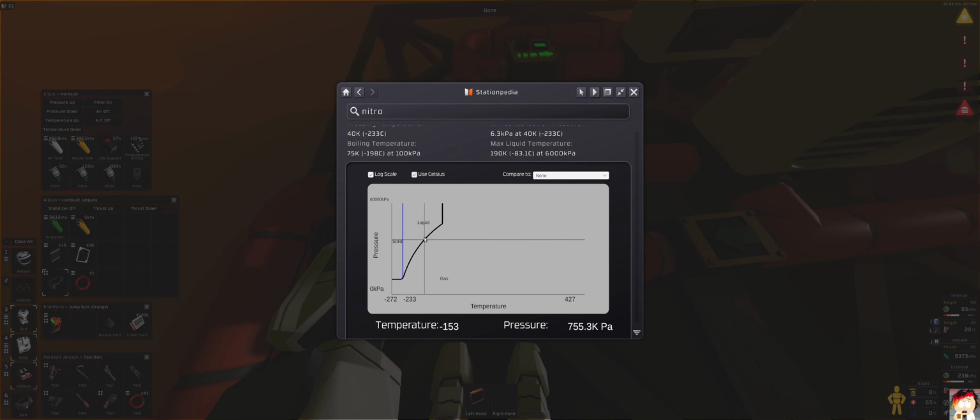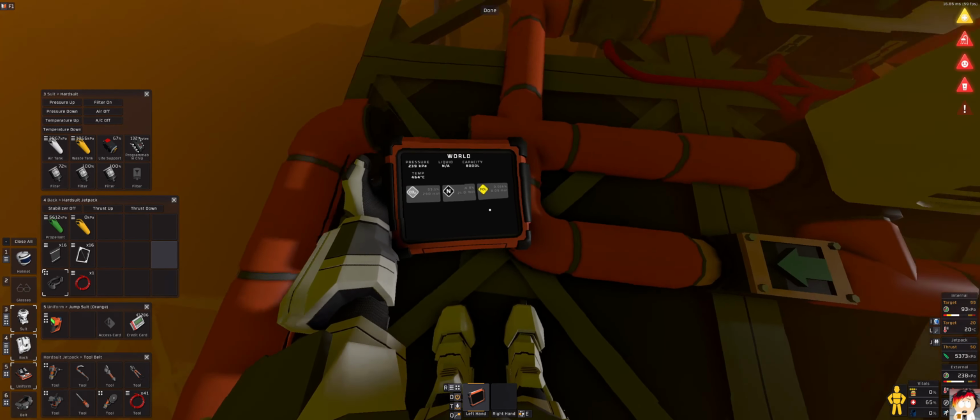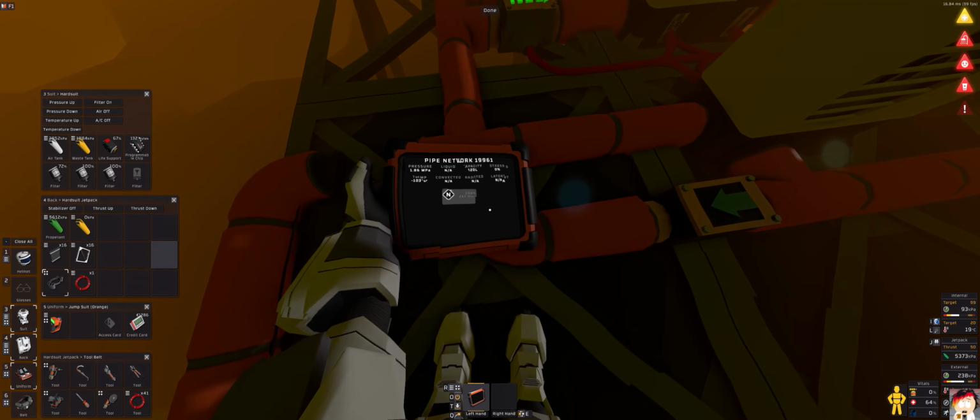We're gonna have there a little bit above 2 megapascals of pressure, so you can see a temperature of 119, 120 centigrade is when it will be liquefying. If the pressure is lower, I can go to a lower temperature, right? But it's a little bit pointless. At 70 kPa, keeping that pressure, working with something like this is problematic, right? So dropping below that temperature, it will cause liquid to occur in this pipe, and it's gonna go that low, right?